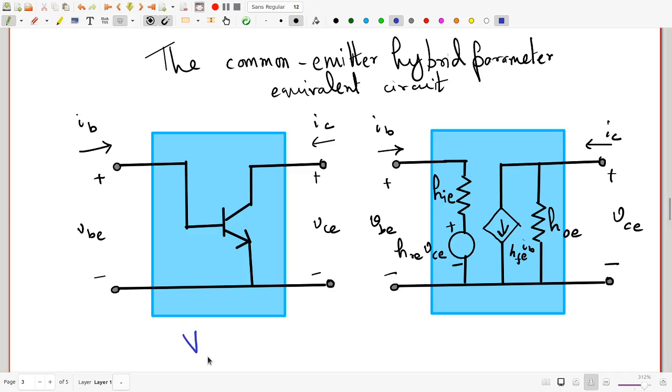the actual voltage VBE, the base emitter voltage, is actually a sum of two pieces. The DC or quiescent point value, which is really denoted by what I've written down right now, or VBEQ, plus a variation which is the so-called AC value, and that's written using small letters.